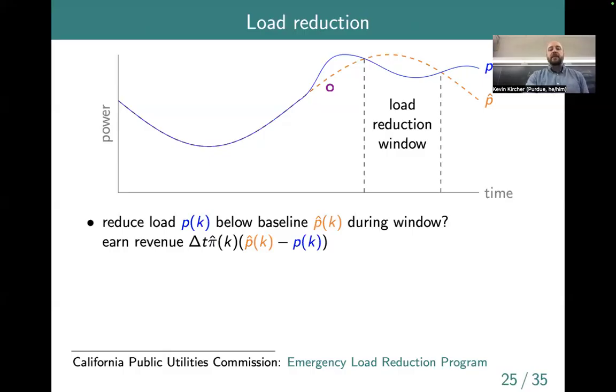Okay, and then we wrapped up by talking about load reduction, or what's sometimes called demand response. This is one of the more common things that people do today. Not necessarily the most sophisticated thing, but a pretty coarse and fairly useful thing, which is during periods when the power grid is really stressed, meaning demand is really high, almost at the limits of what's available on the supply side or in the transmission grid, a utility or some other grid operator would send out a signal.